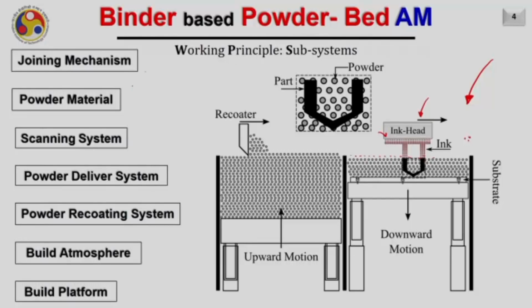However, in some cases the post processing may not be required. The particles can properly join together and they usually have sufficient strength. So for example, if you have a cement like material and you are dropping droplets of water onto it, then you know that after a period of time the powder particles of the cement are going to join together and become hard, and then no further post processing may be required. So as you have seen, it typically depends on what kind of powder and ink material you are using in your system.